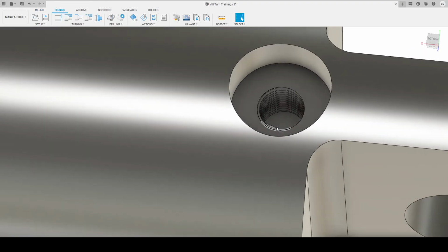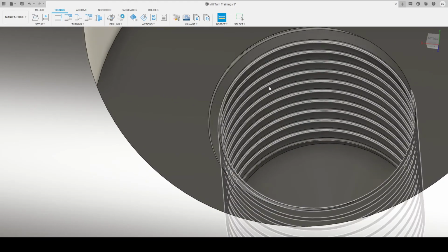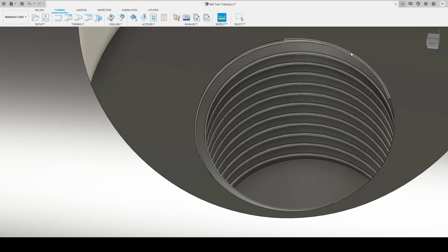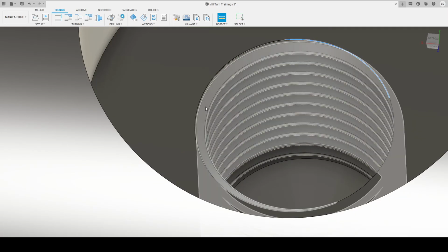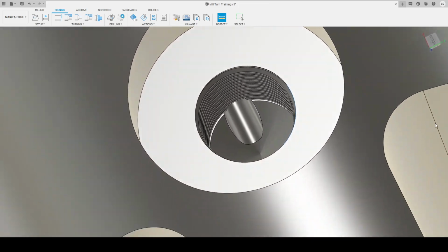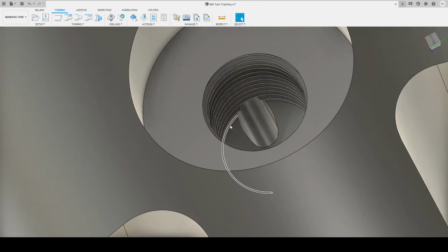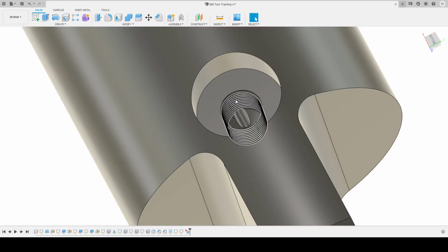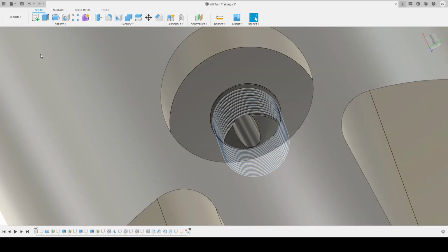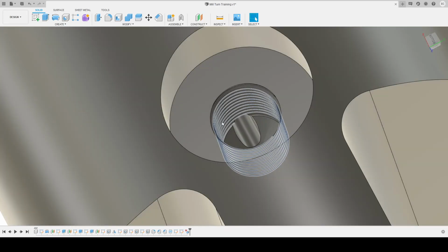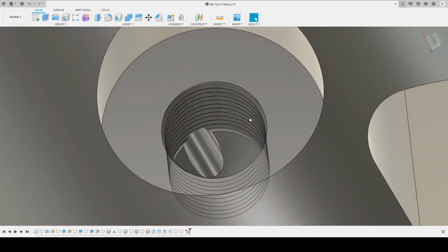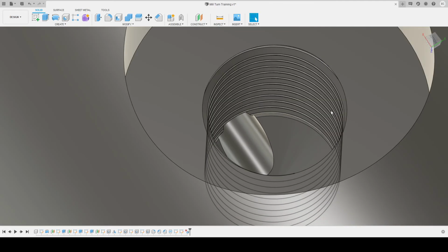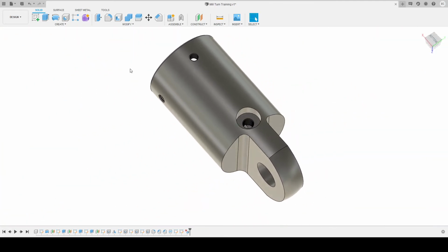Now we want to drill this hole. So the diameter is... why it's a little bit tricky when you model the threads. So I think it was modeled before you turned on. Yeah, it was modeled before the design history was captured. So what we can do, and I don't have the drawing on me, so let's say it's 8.7, which I think is probably just a 1/8 BSP hole.